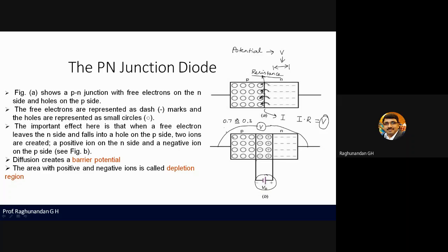When this current flows across this resistance, a potential difference is created. So finally we say that this barrier, a junction which separates two things, offers some potential. That potential is known as barrier potential. Then what is the standard value, 0.3 or 0.7?